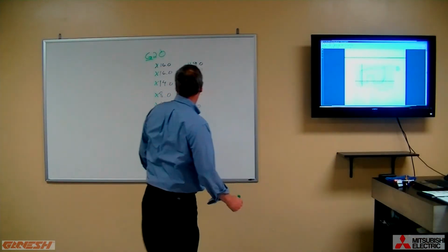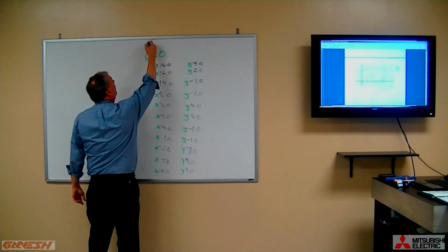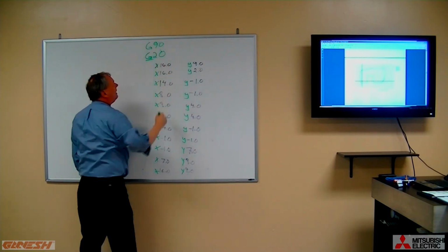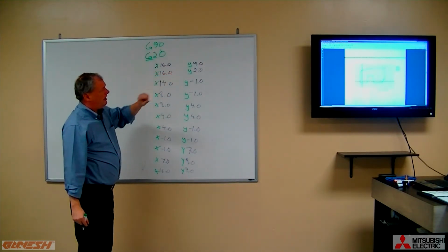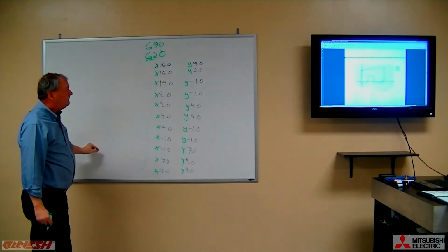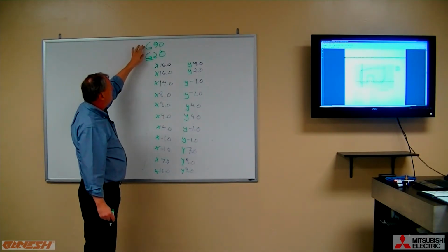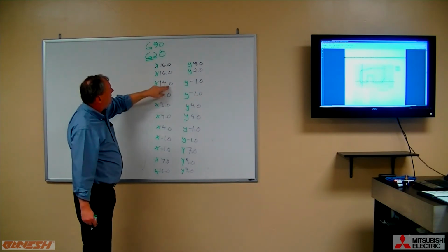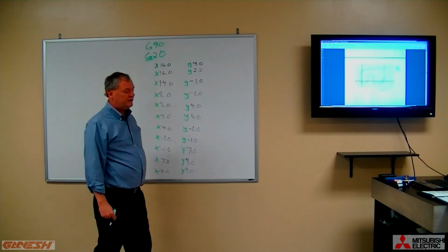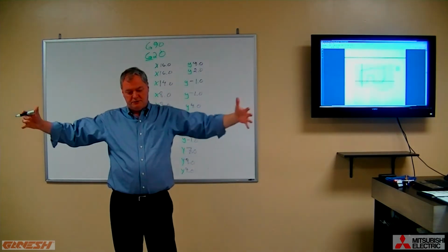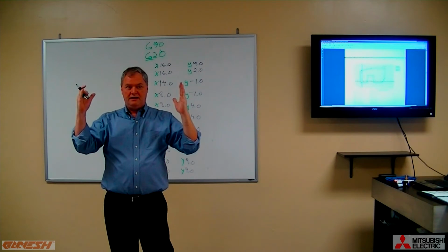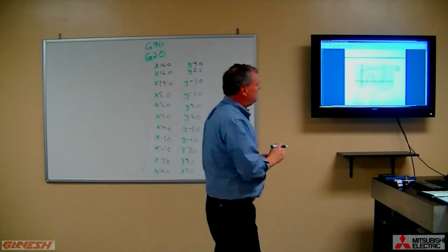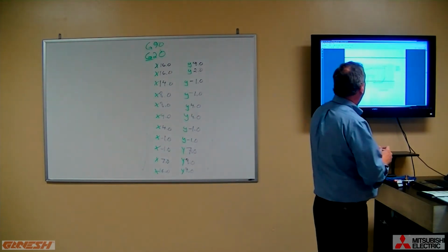What we would do is tell our control that, hey, all the coordinates that follow are absolute values from an origin point. So we tell the control G90, and then we tell it G20, which now says, okay, all of these values are actually inches. So the machine will make a 14-inch move, which might be something this wide, as opposed to a 14-millimeter move, which would be something much, much smaller than an inch. Maybe roughly half an inch.